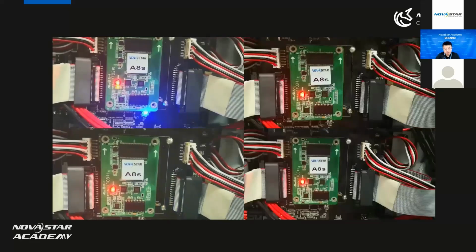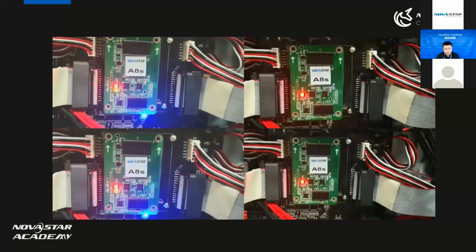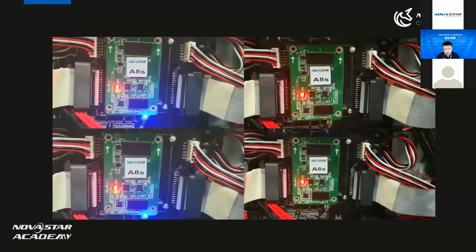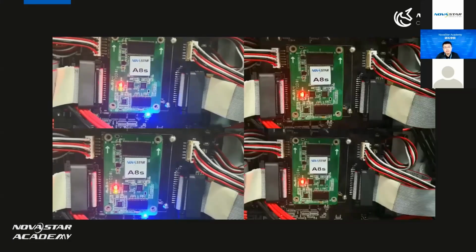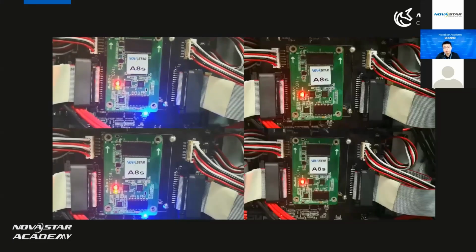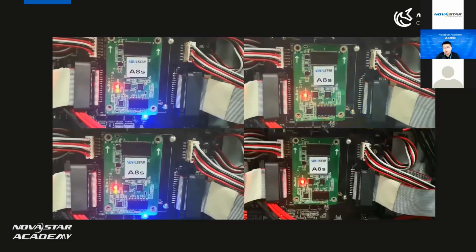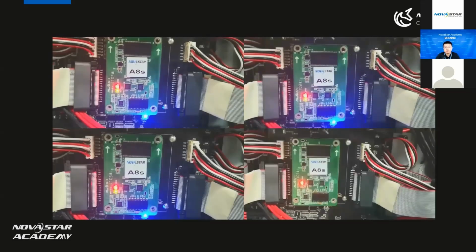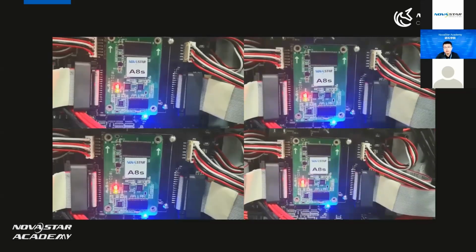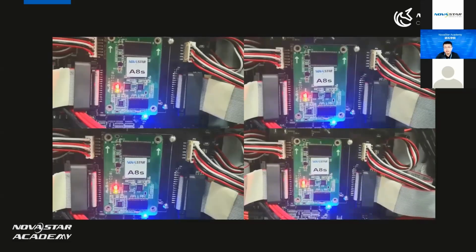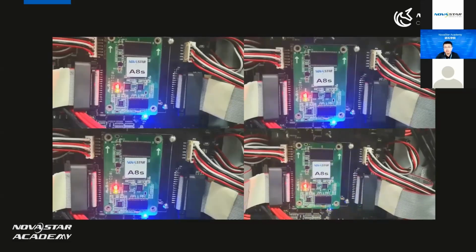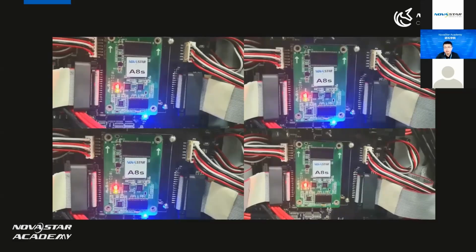And the top left corner is in backup mode because you can see it fast flashes 4 times and waits half second. How about this one? This is working normally because it flashes once per second. And this one is no video source connected. It fast flashes 3 times and waits half second, and then another 3 times.